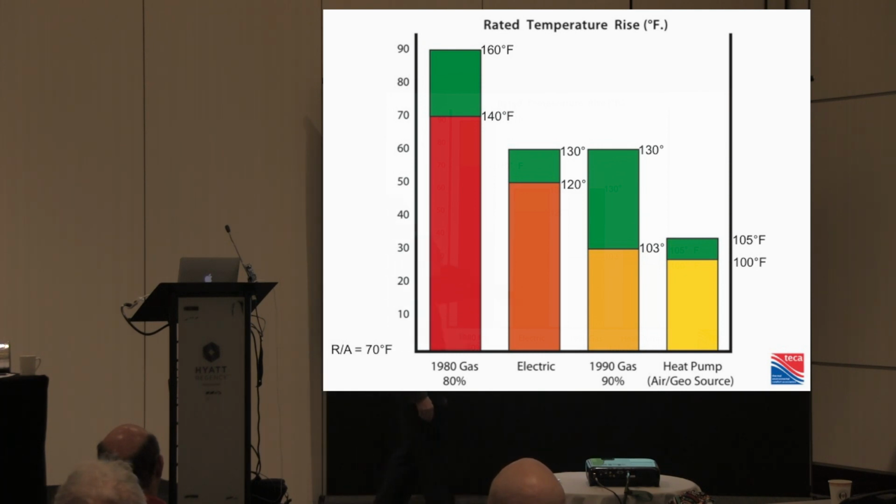You take a look at a gas furnace today, the new high-efficiency ones, the cheapest, fastest way for the manufacturer to meet the mandated efficiency requirements on furnaces is to put a big blower in the cabinet, because if you sweep a lot more air through it, you can scrub off more heat, and indirectly you're meeting your efficiency requirements. In the same way, if you stand out on a cold winter day, the more the wind blows, the more it's stripping heat off your body. We do the same thing with a fan and a furnace.